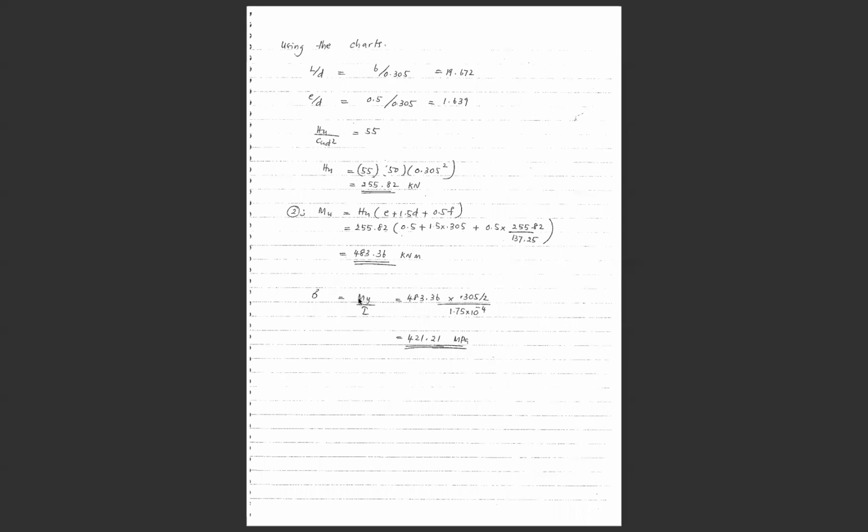So you just need to substitute the value we calculated now from question 4 into these equations, and that will give you the value of maximum stress on the system. Y will be the same, which is half of the pile diameter, 0.305 divided by 2. The moment of inertia we have already worked out last semester, which is the one here.